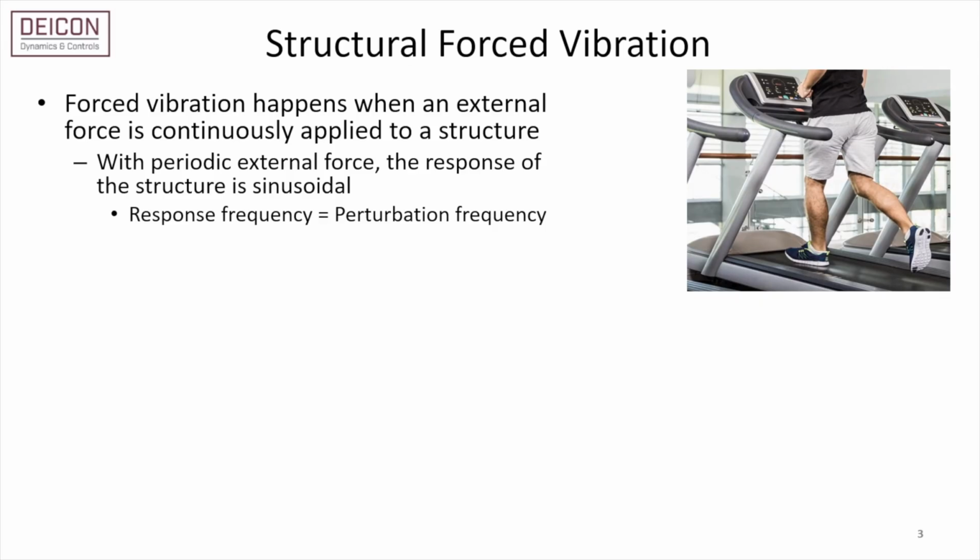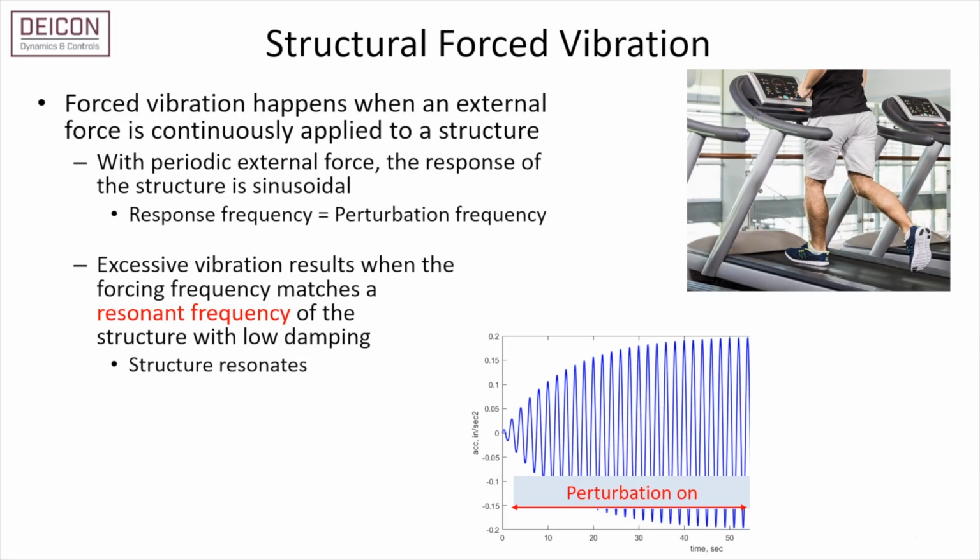When the frequency of a repetitive external force aligns or comes close to one of the natural frequencies of a structure, resonance occurs. At this point, the structure starts vibrating excessively. Initially, as the perturbation begins, the vibration within the structure also starts. This vibration gradually builds up until it reaches a steady state level where the amplitude of vibration becomes constant.